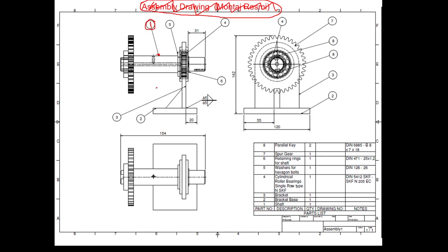Some companies use this measure: which one is the highest cost, then say it is the one, and the cost of this one is less than the other, so say it is 2, and so on. But some other companies use not the cost but the volume. The component with the highest volume, the greatest object in size, is called number one. Okay. The reader looking at the balloons can see their identifications, ID numbers.